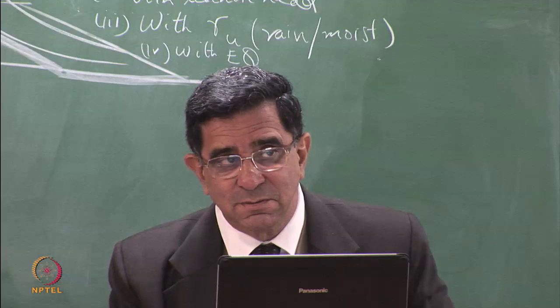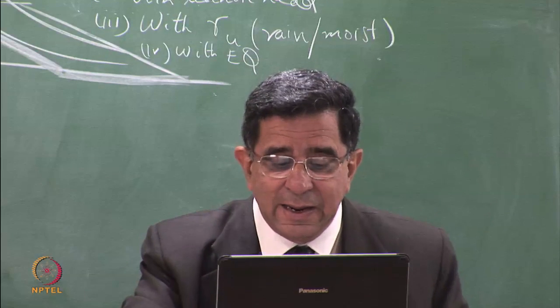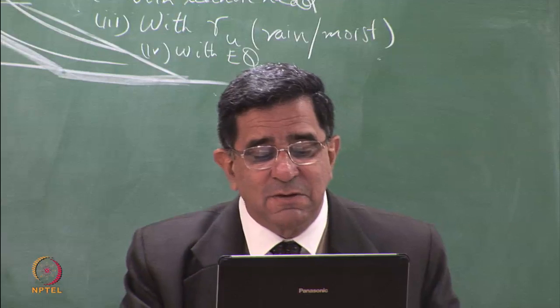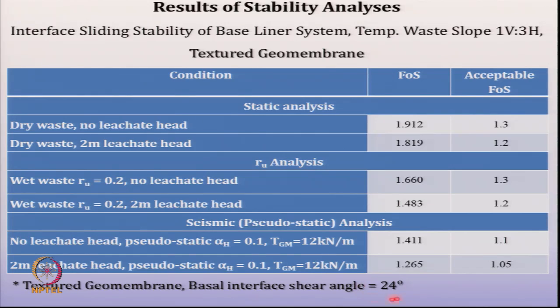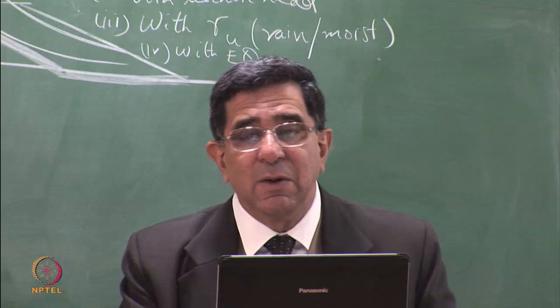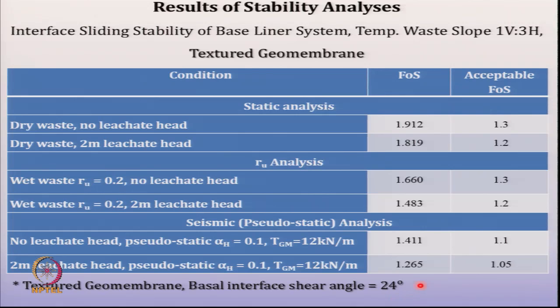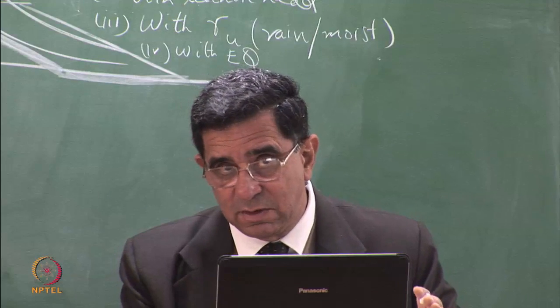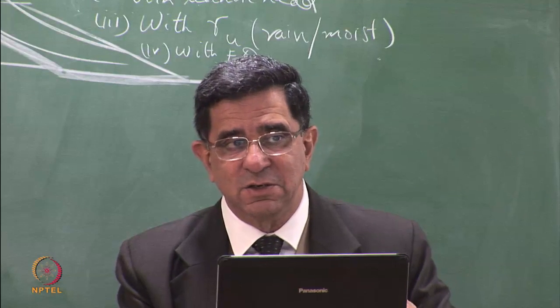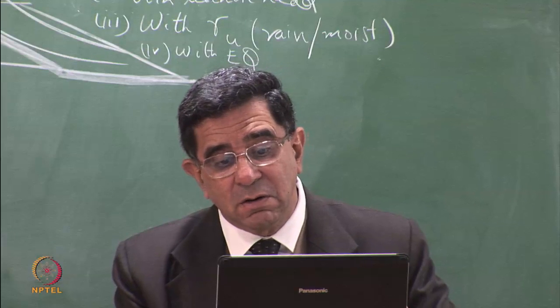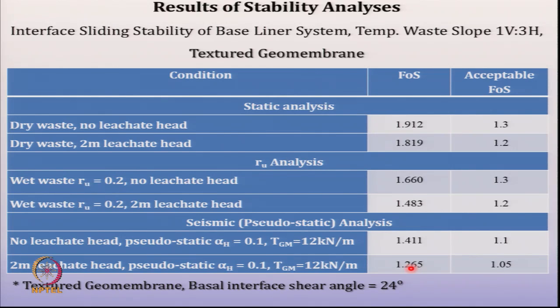good values. Now I thought that one of you would ask me this question: how did you use 24 degrees for textured with clay, because I have given you the table, and it is typically 10 to 15 degrees. Well, this stability analysis was done by an overseas consultant, so they have given us this value. We told the owner that we think it should be about 18 degrees. But if your consultant is underwriting this, it's fine.